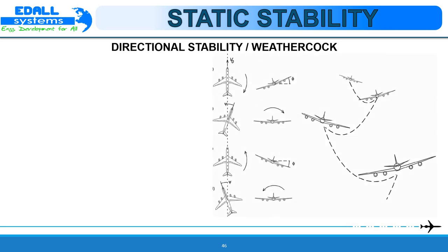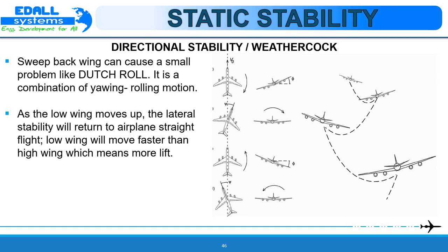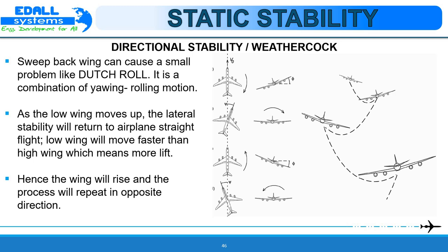The Dutch roll mode is a classical damped oscillation in yaw about the z-axis of the aircraft, which couples into roll and to a lesser extent into side slip. The motion it describes is therefore a complex interaction between all three lateral directional degrees of freedom. Fundamentally, the Dutch roll mode is the lateral directional equivalent of the longitudinal short period mode.